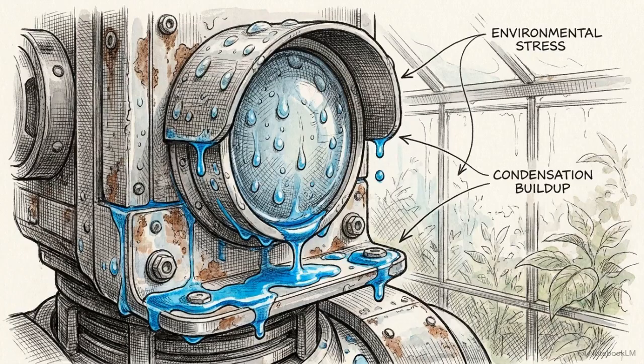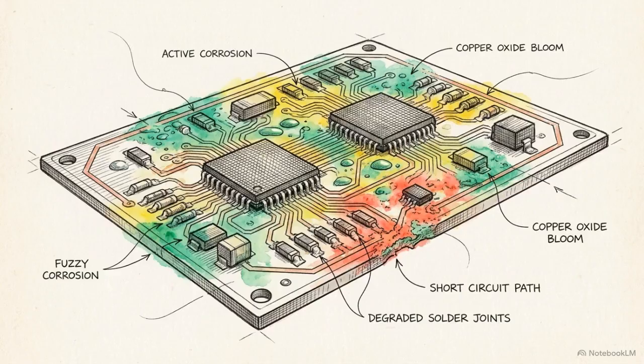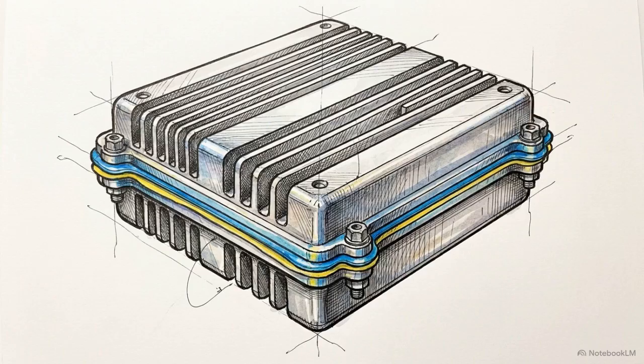Inside those narrow rows, the robots face a second, more destructive constraint, a persistent relative humidity hovering between 80 and 95%. This continuous moisture actively degrades standard commercial electronics. Without specialized protection, the mean time between failures for edge computing hardware drops to under 200 hours. Engineers have to hermetically seal the electronics.